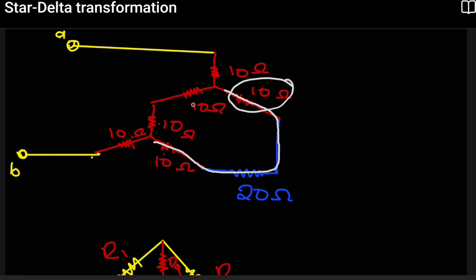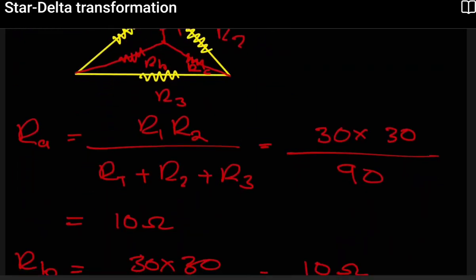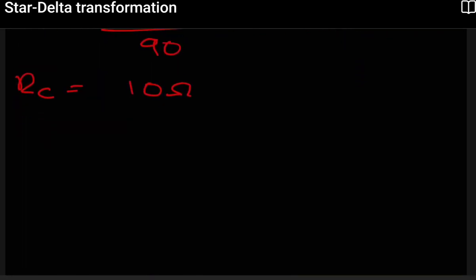And apart from that, observe that this line as well has a 10 ohm resistor and a 10 ohm resistor here. So these two are in series. We haven't found any junction so far. So those two are in series. So let's redraw our circuit showing only the series, only the simplified versions in each line.